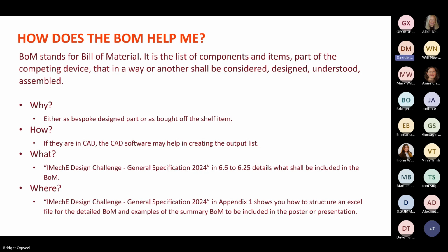So, how does the BOM help a student? It is normally something the students don't spend too much time on, and they may not understand how it could help them. Now, why should I have a bill of material? Well, to decide if I need to design a component that will be built or manufactured in the university or college facility, or if instead I could buy it off the shelf.